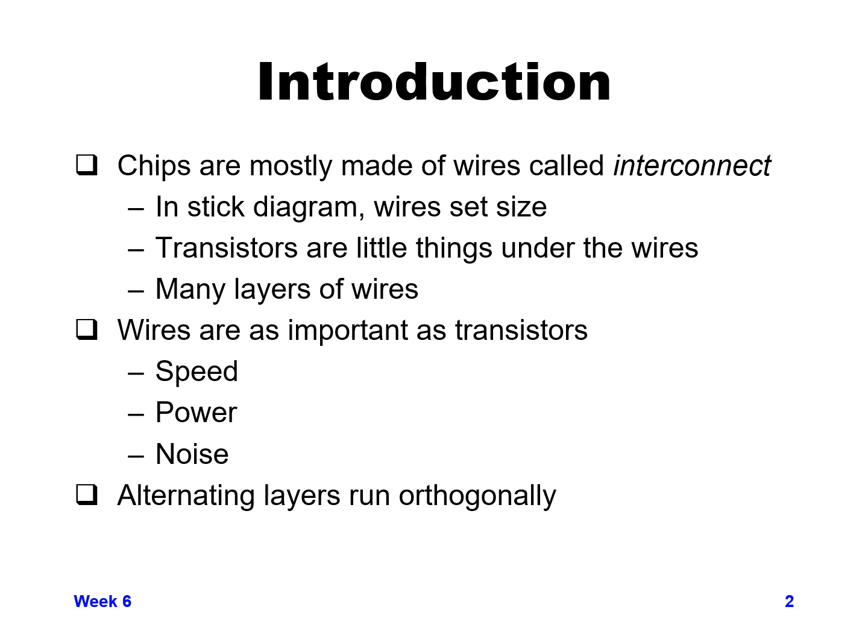And so in reality, the wires can make up the size and the area that you're consuming as much, if not more, than the transistors, depending on the situation that you're in. And like I said, there's many layers of wires. There's only one transistor layer. So in effect, your wires really are as important as your transistors in speed and power consumption, and also wires will introduce noise that you have to account for and try to make sure you introduce as little noise as possible.